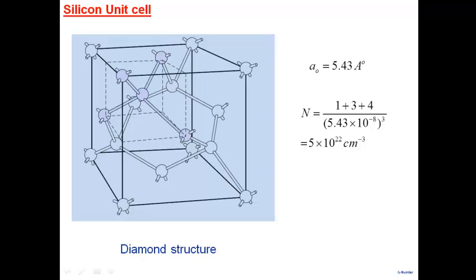And so you can see, if the silicon atoms are 5 times 10 to the power 22, and you are adding 5 times 10 to the power 16 impurity atoms, you're basically adding very, very small amounts, in parts per million here. So the other thing is, note that this is a whole crystal, and we're talking about how many atoms